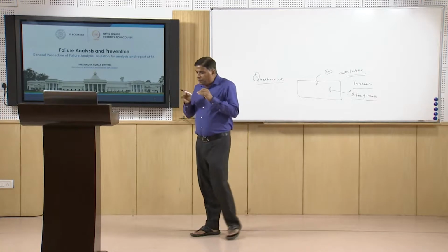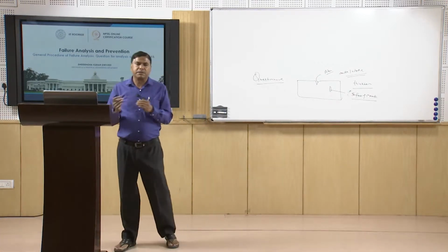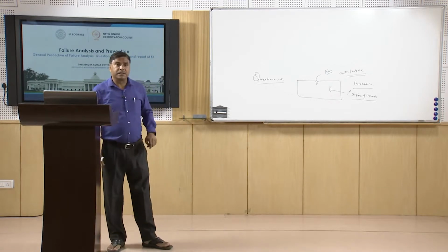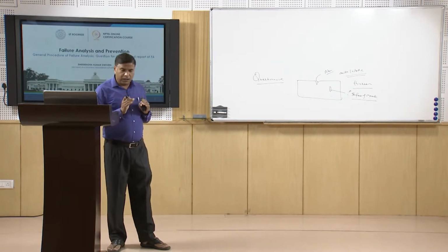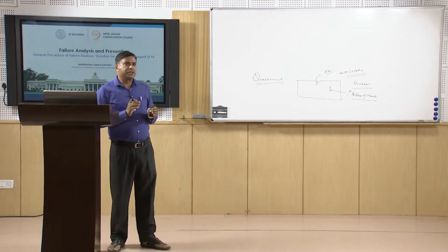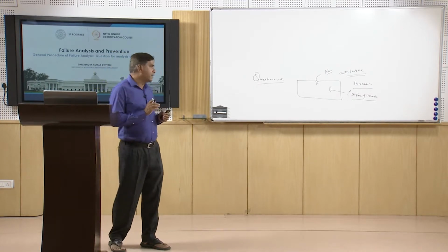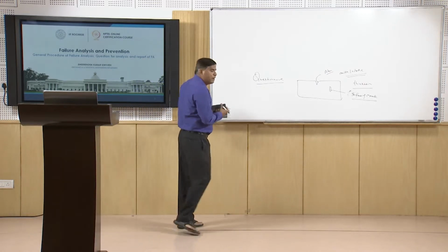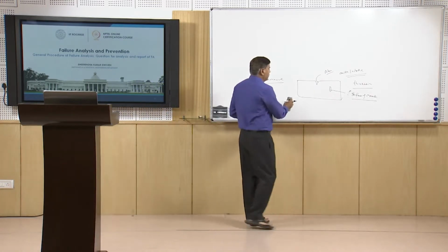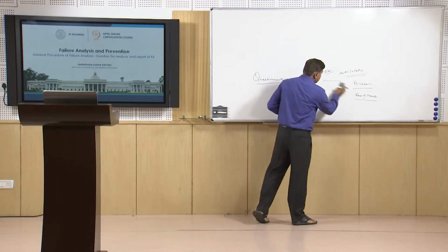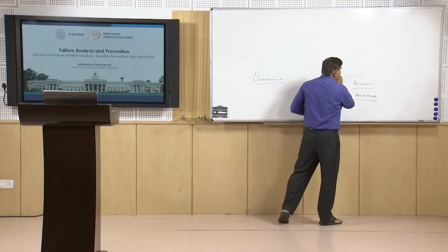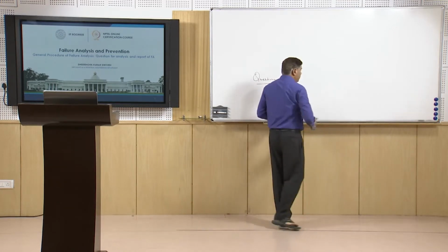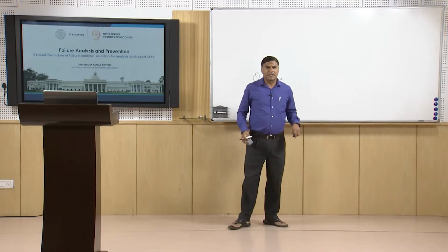So we also need to identify if the fracture has been caused due to cracking, and whether the cracks were present at the surface or in the subsurface region. Also, we need to establish if there was any role of stress raisers in facilitating crack nucleation. These stress raisers may be in the form of the toe of a weld, a location where a change in cross section is taking place, or a keyhole, keyway or any other kind of hole which is acting as a stress raiser.